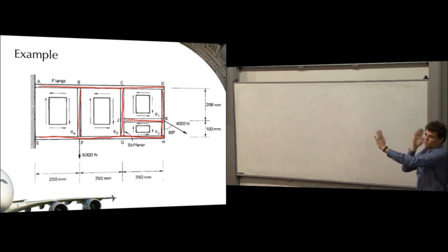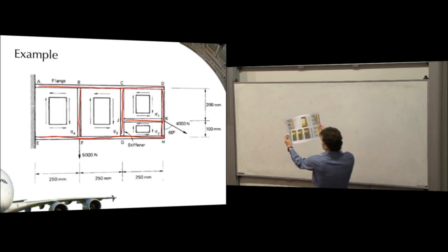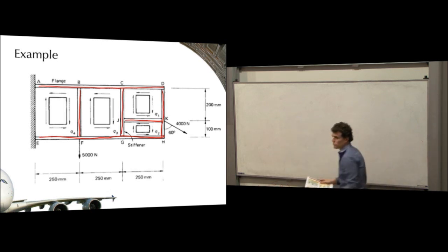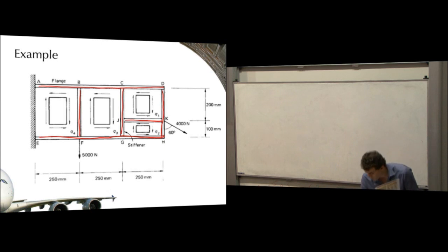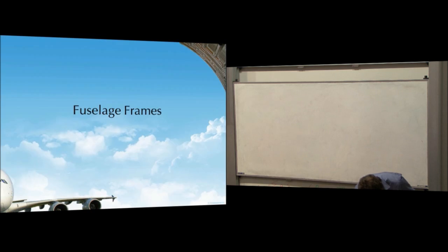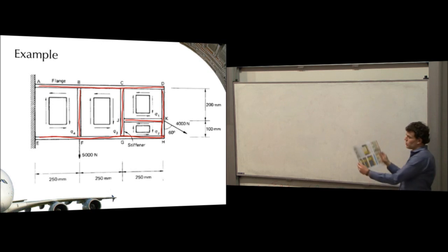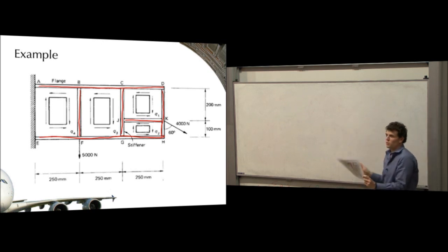Now there's actually material. There's a shell that's sitting like this. It's actually carrying our shear forces. Okay, and we denote that in problems by drawing these internal shear flow pictures. So if you see one of these in a problem where someone's drawn these little internal shear flow diagrams, you know that there's actually material there. There's not meant to be a hole.